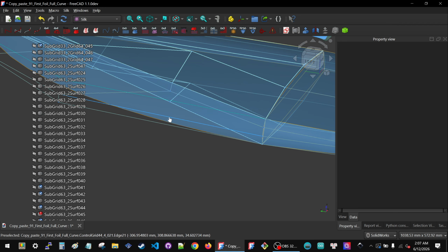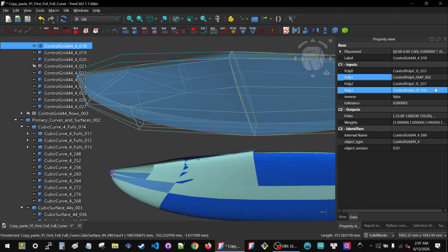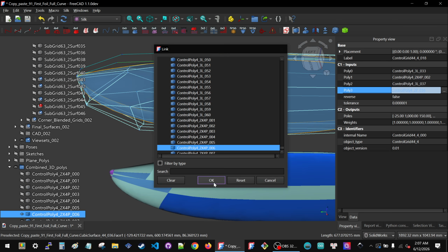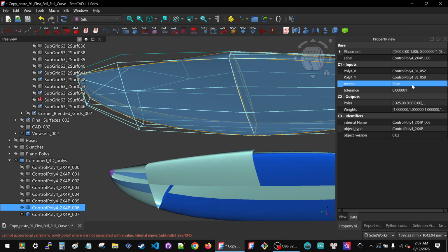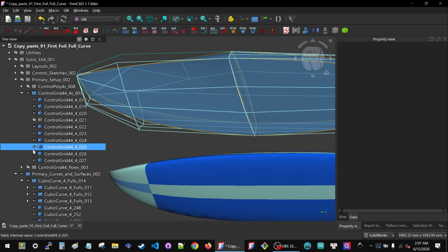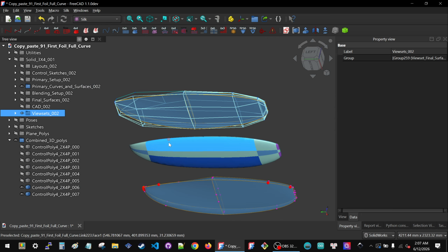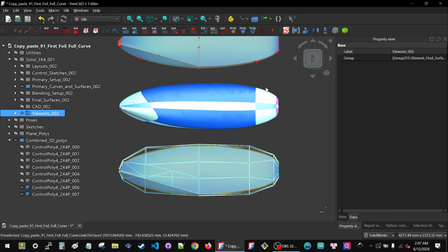Okay. Hide that grid. Go to the bottom face. Swap out 16. Which one? The bottom one. I still have errors. Go to here. Reverse. True. Errors are gone, but don't trust it. Check the view set. Yep. I have the bottom edge. I have my full outline. With my bottom rail, I just need to fix my top rail.